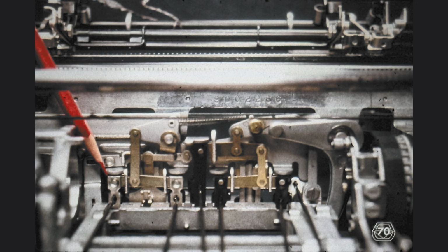Observe also that once the tilt pulley sector is rotated, the link which connects the sector to the tilt ring causes the tilt ring to rotate by 1 tilt increment. 1 tilt increment being the angle of rotation needed to position the T character from the second band of characters on the type element in line for printing.